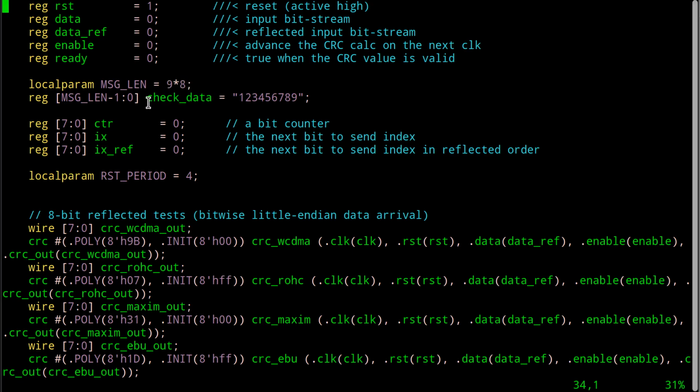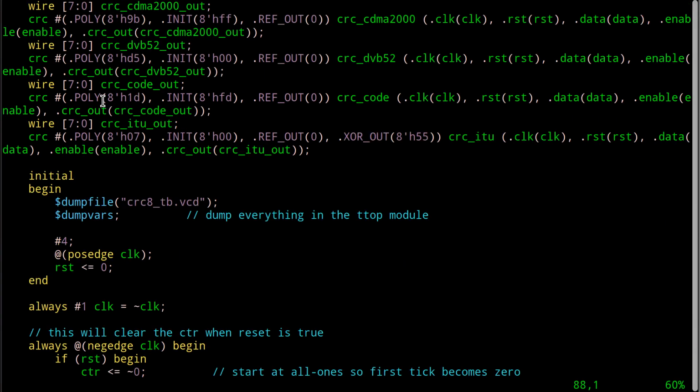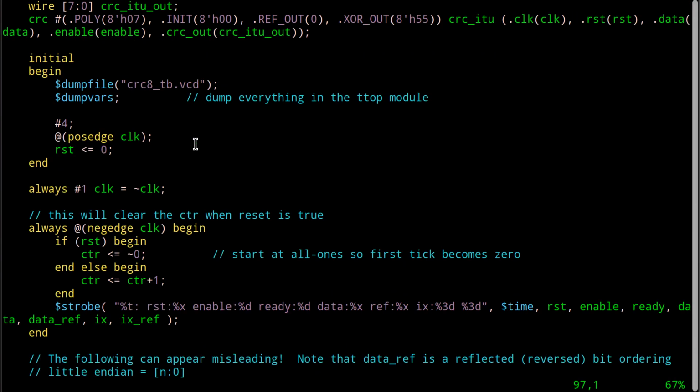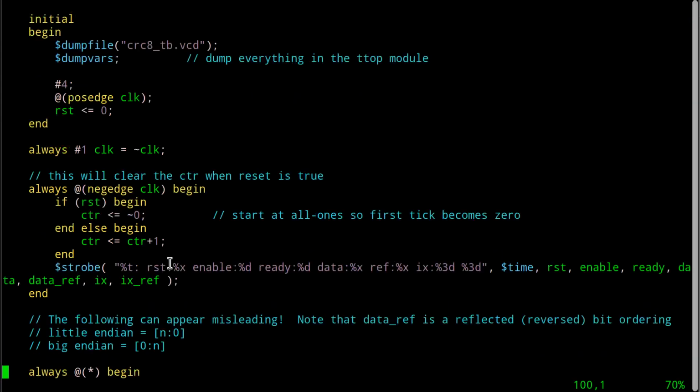Now we have to be careful, because what's the order of all these bits if I initialize it this way? It might have been easier to just initialize the whole thing in raw binary, although that would have been an enormous thing to type in. I'd probably do it wrong. So you can see the artifact of this whole thing. This check data vector is one big bit array, and when you go down here and look at the test logic, what happens is